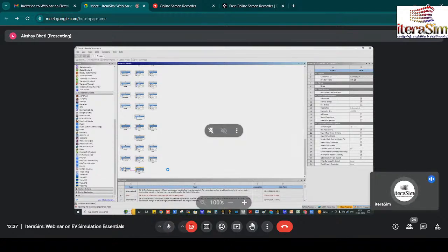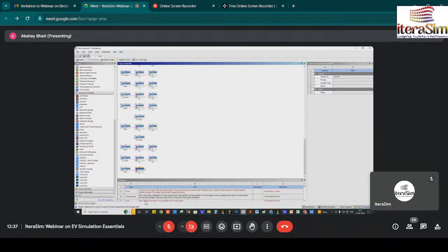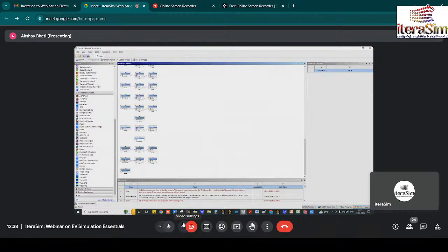So after this blade creation, you are using the mesh modeler. After that blade generation, we need to consider designing the entire fan, because basically in the design modeler we can generate a blade. After that, we have to pattern every blade. Let's say we are developing a fan with 8 blades. So in design modeler or any design software, we will do that setting and we can develop any fan over there. Yeah, I will show you one thing.